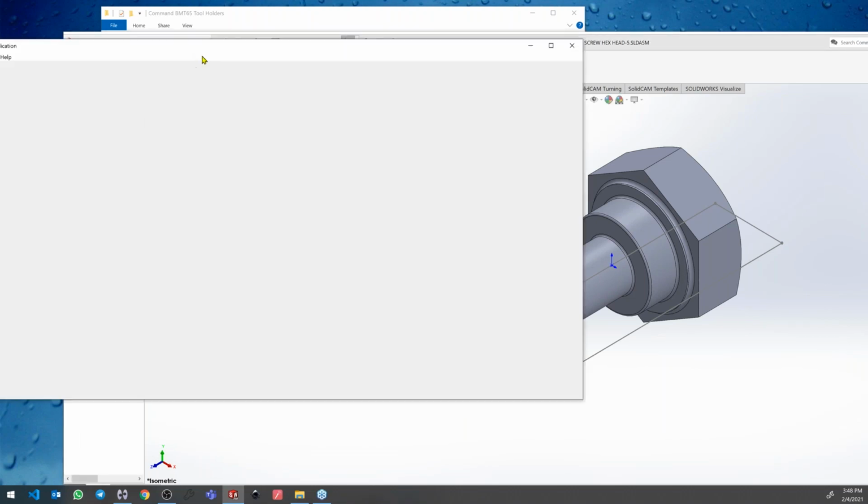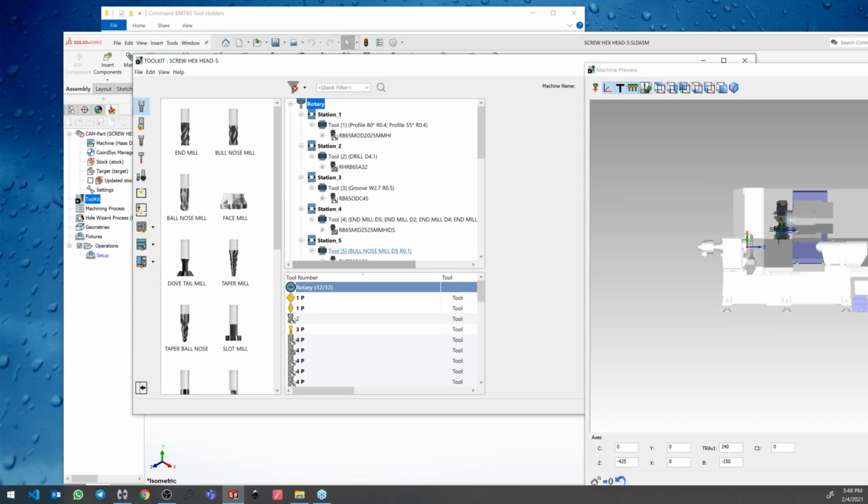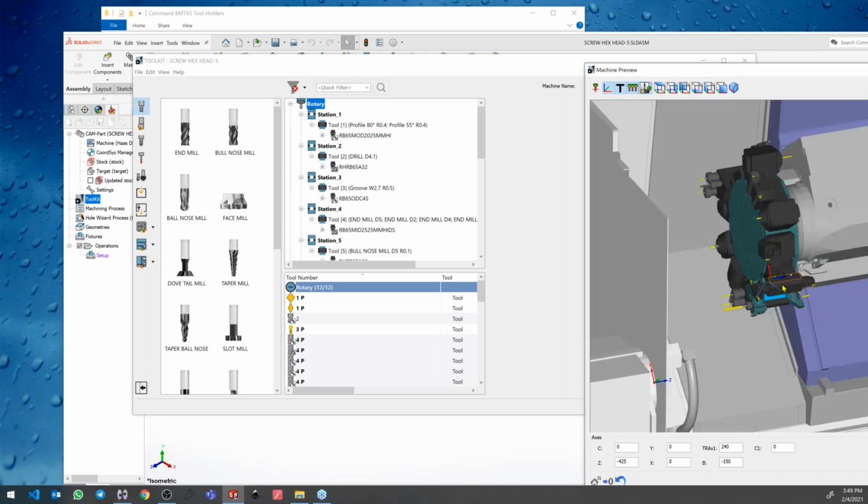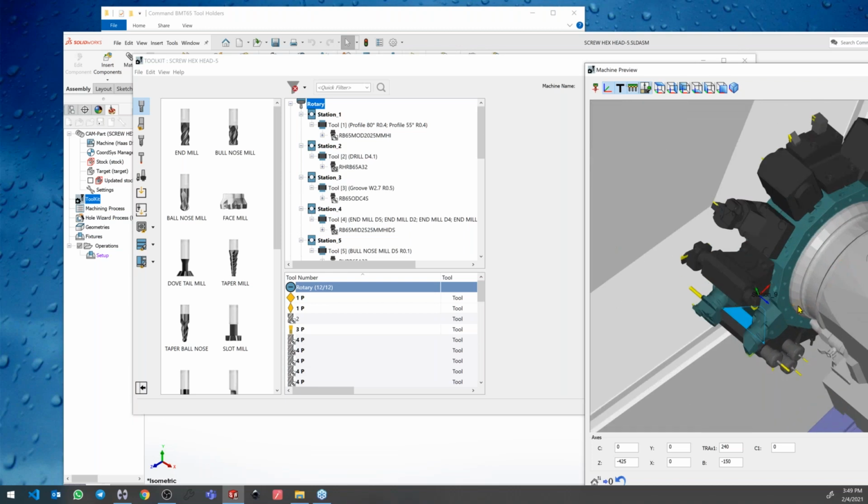Once you go to the tool library here, you will see all your setup is already here. I showed it the long way. The proper way is, of course, if you have a table of what you want to use for any setup, it's predefined. From my experience, 80% of the tools you hold on your rotary turret never move. It's the general groove tool, cutoff tool, normal generic rough or finish tools. They always stay on the stations. And of course, as you see here, I have already predefined setup, and I can use it for this part.